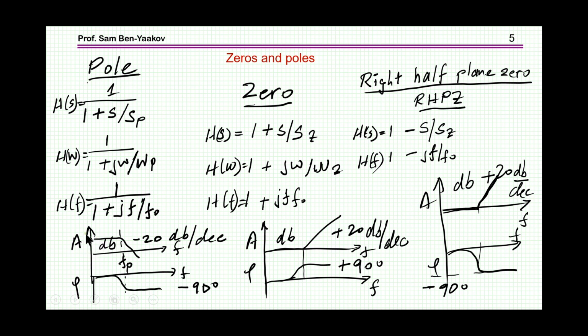It goes flat up to the point of F0, F pole, it should be here F pole, and then it goes down by 20 dB per decade. What is 20 dB per decade? 20 dB is 10-fold, a decade is 10-fold, so it's reducing by 10 for every 10-fold of frequency, and this is again in logarithmic scale, dB, so therefore it is a straight line in logarithmic form.